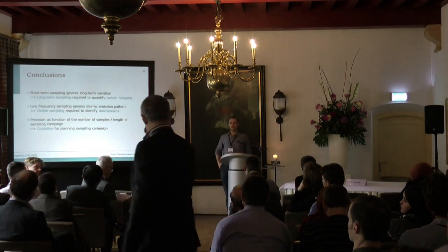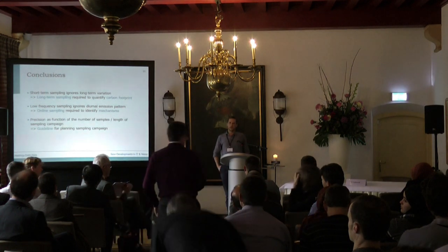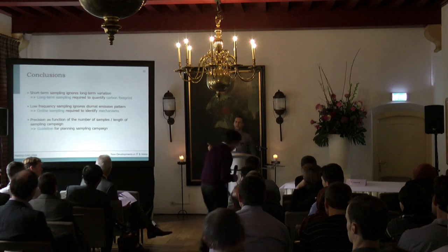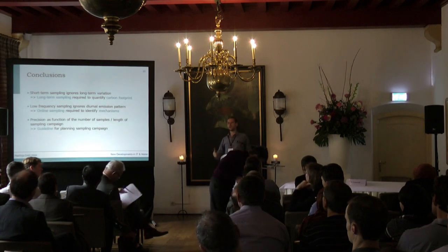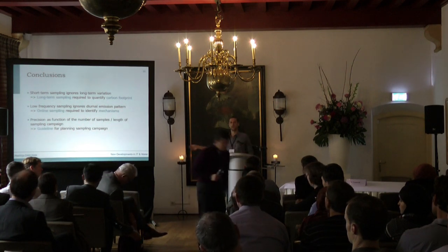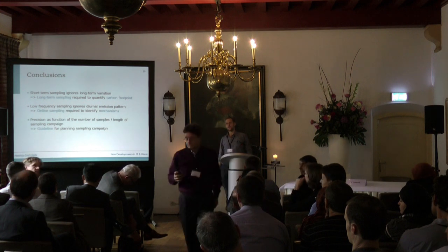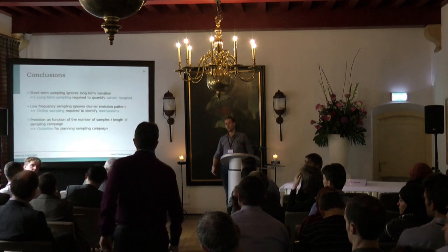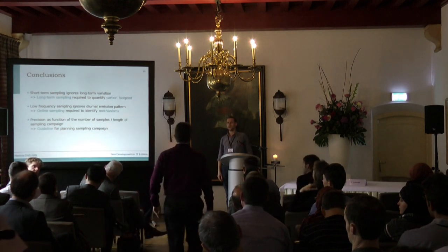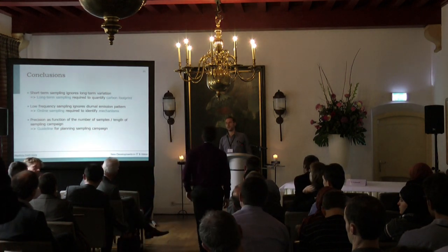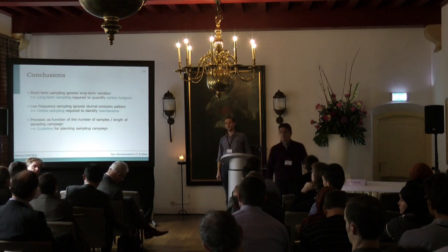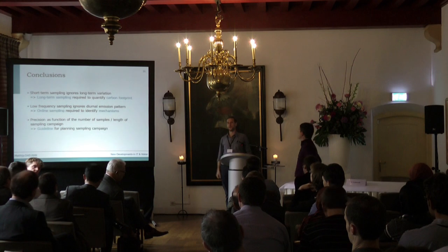But then, the problem with the floating hood is that you will of course have this temporal variability, but you will probably also have spatial variability. So you have an extra concern, because the nitrous oxide will be different in different places of your tank. I think it's a very fortunate situation to have a covered plant, but sometimes you have to resort to a floating hood, for instance. But then you have to take care of the spatial variability too.